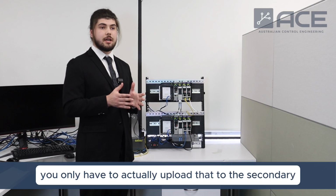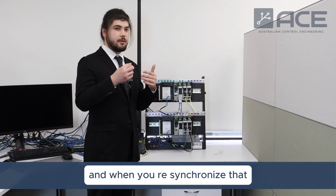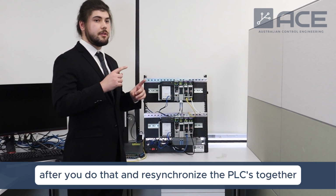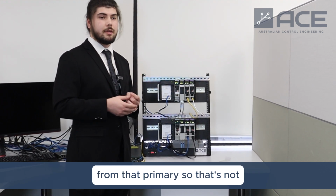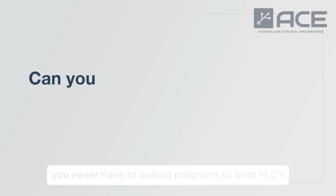Yeah, just the program. You only have to actually upload that to the secondary, and when you resynchronize, you still have to perform that lock switchover. That's an important step. After you do that and resynchronize the PLCs together, that program is automatically loaded to the secondary from that primary. So you never have to upload programs to both PLCs.